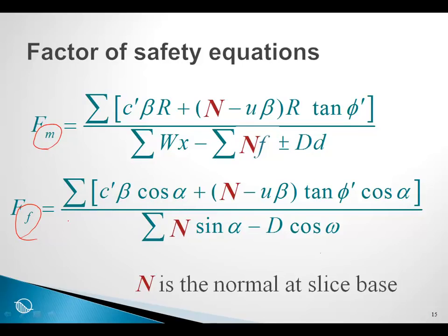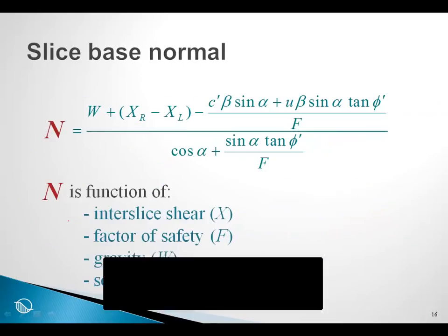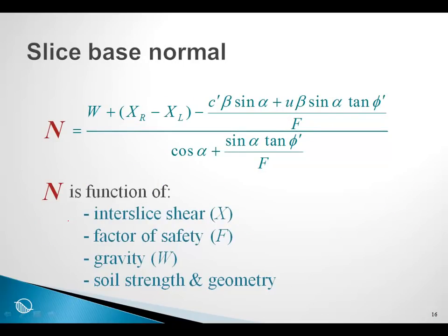I will not dwell here on the details of these two equations except to note that the normal at the base of the slice occurs both in the numerator and in the denominator of the equations, and the normal occurs in both the moment and force factor of safety equations. Here is the equation for the normal at the base of the slice, and it's worth spending a few moments on this equation.